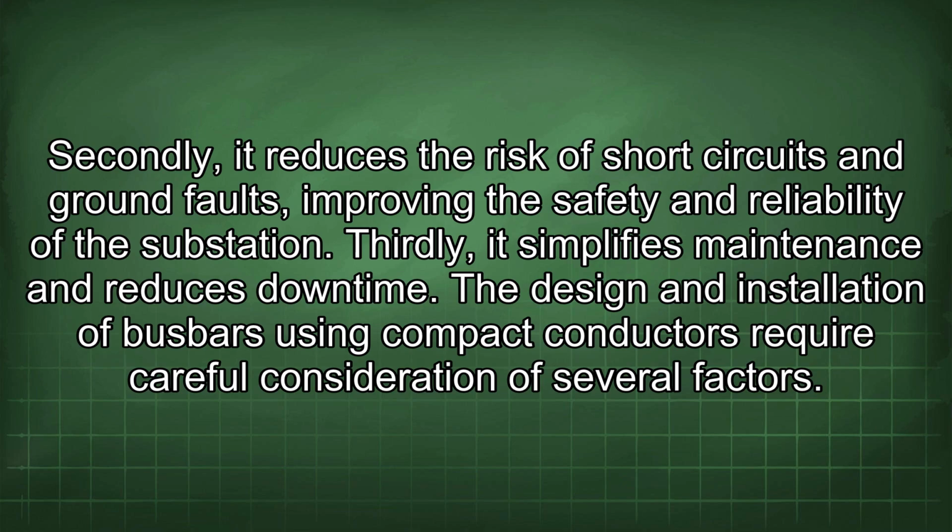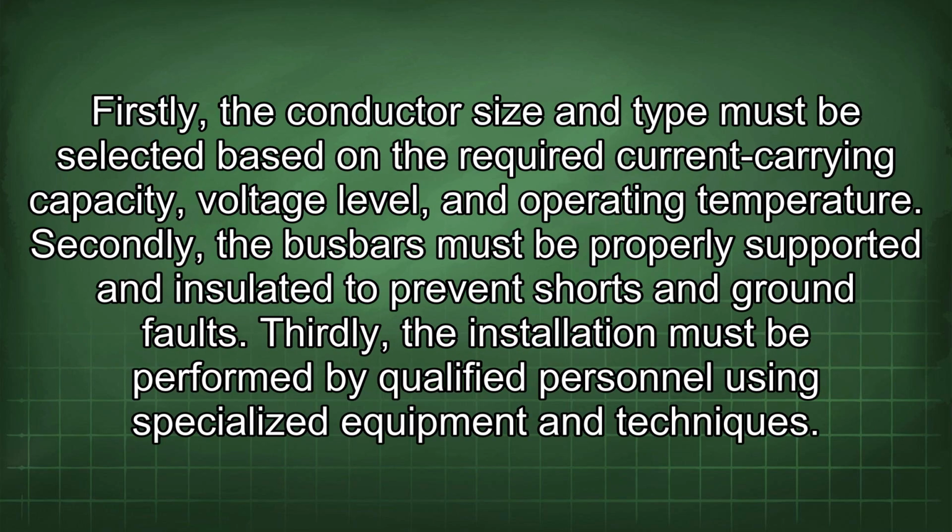The design and installation of bus bars using compact conductors require careful consideration of several factors. Firstly, the conductor size and type must be selected based on the required current carrying capacity, voltage level, and operating temperature. Secondly, the bus bars must be properly supported and insulated to prevent shorts and ground faults.